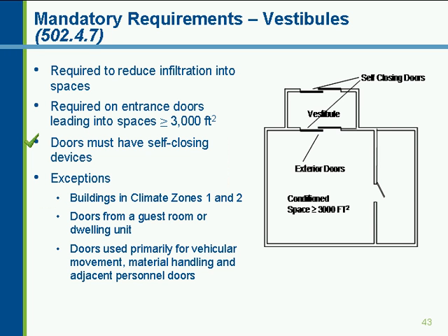And the vestibule has to be designed so that both doors do not have to be opened at the same time to exit and enter the vestibule. So, for example, in the picture I have here, the door leading from the conditioned space and the door leading to the outside at the other end of the vestibule would not have to be opened at the same time in order for me to pass through. The whole goal of a vestibule is to create an airlock. So you would enter the vestibule, have the door shut behind you, and then exit the vestibule and have the doors open in front of you to exit that building. That creates that airlock.